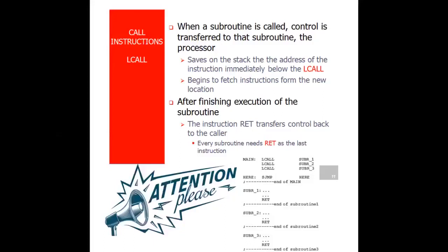Okay, so after finishing the execution of the subroutine, I have to write the instruction RET, which means return, so that it will execute the instruction and come back to this particular memory location from where I have to execute my main program. Okay, so it is the commonly used subroutine, that is LCALL subroutine 1.